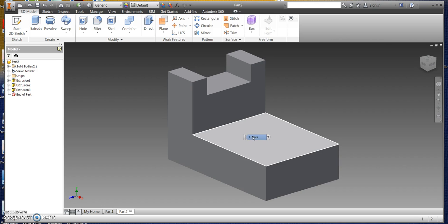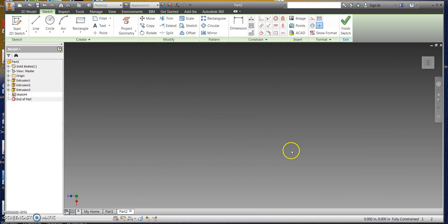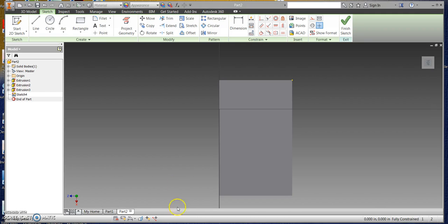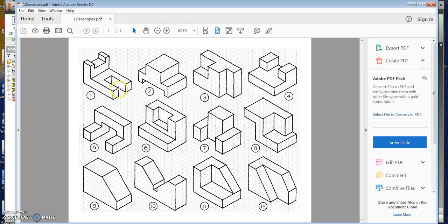Then the final thing, and I'll go real quick, I think you probably get the idea by now. Now we want to click in this face and cut a rectangle all the way through. So I'll click in this face, go here, and that highlights it or moves it for us. Now this one's kind of hard to tell, but I know that I need a rectangle that is 4 inches in width. And in this direction, it's 1.5 from this edge and 1.5 from this edge.